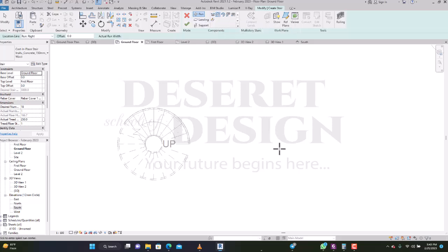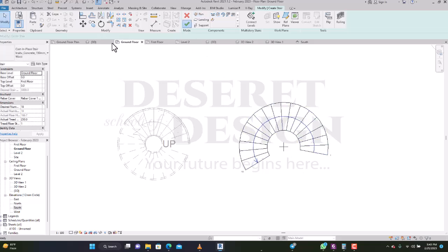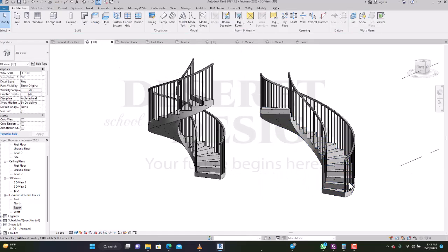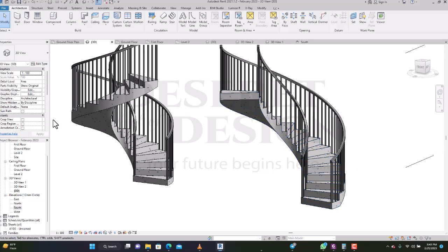So let's say another spiral. I'll click, but this time around I'll give a more gentle radius. Okay, so a bigger radius, then I'll accept. Do you get it? Then it comes with your what? Railing. So for this one it's the same 18. If you want more, increase it before you draw. You need to set it, because if you don't set it, it's using a height to draw. So if you place it and then say, oh, maybe I need 20, whatever you are doing will just be added. So it means that 18 has taken you to the floor, but if you add 2, your 2 will be above the floor. It means when you end your stair, you jump down to the floor.